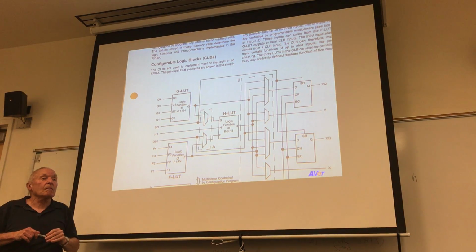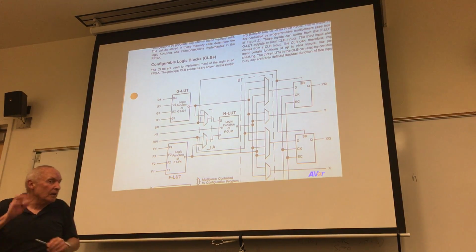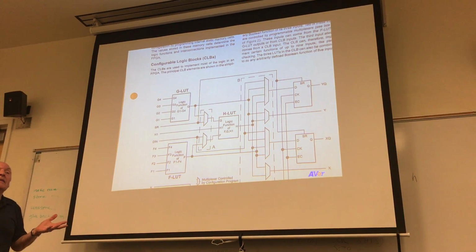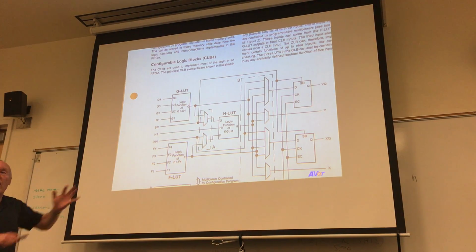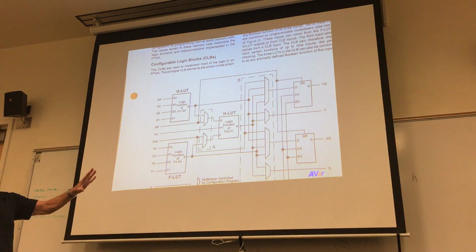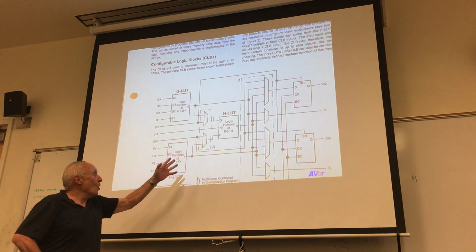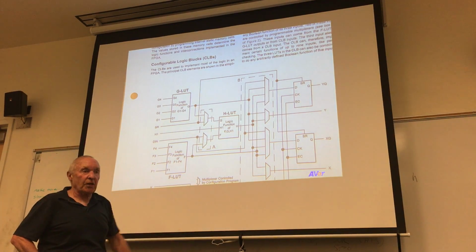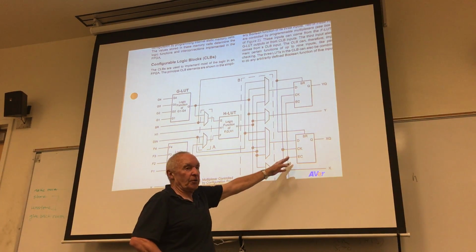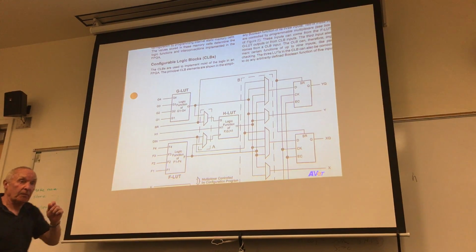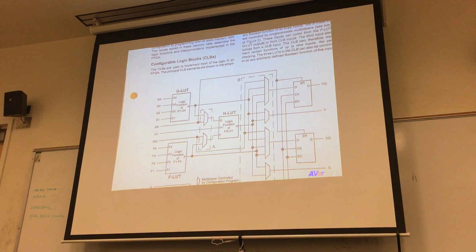Where are the select bits for the multiplexers coming from? That's part of the programming. When you program, and I was just getting to that, one of the things you obviously have to program is what's the LUT's content. The other thing you're going to program is what are the select lines on all these multiplexers that you see. When we get to this circuitry here, you're going to see that you have a couple of other options. This is a simplified diagram of those registers, but we'll get to that shortly.